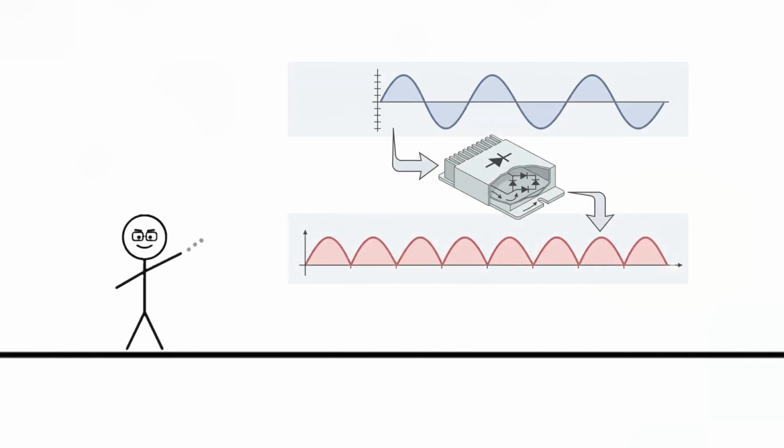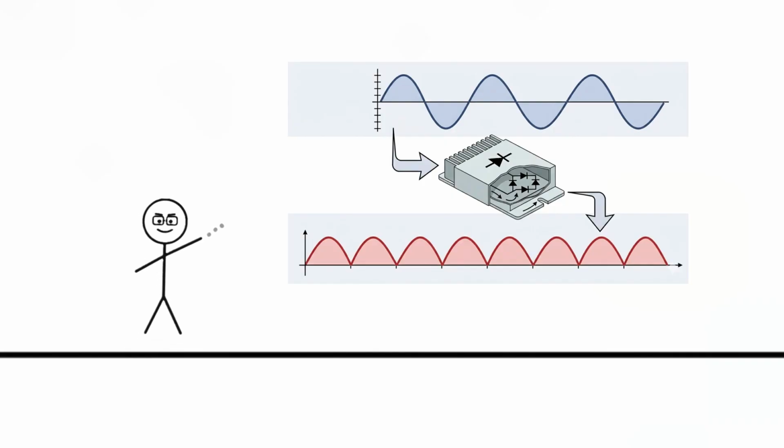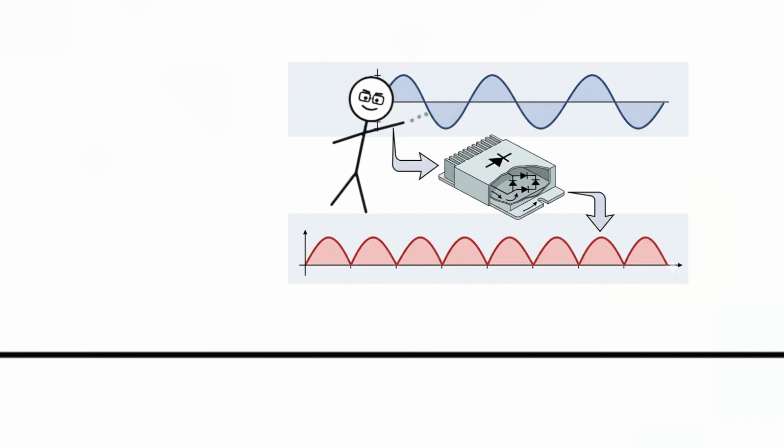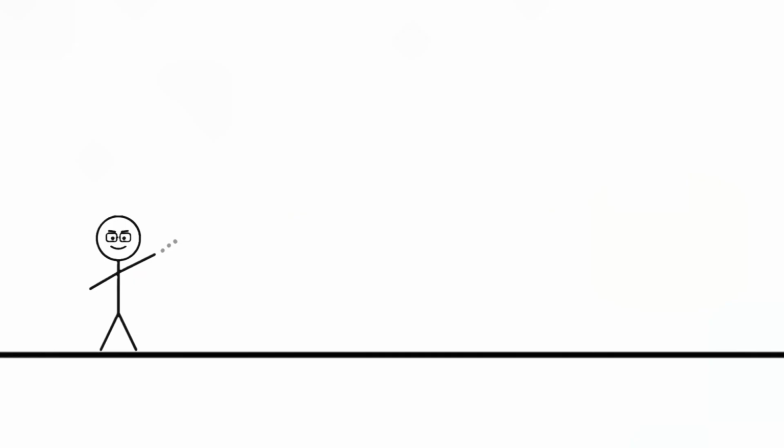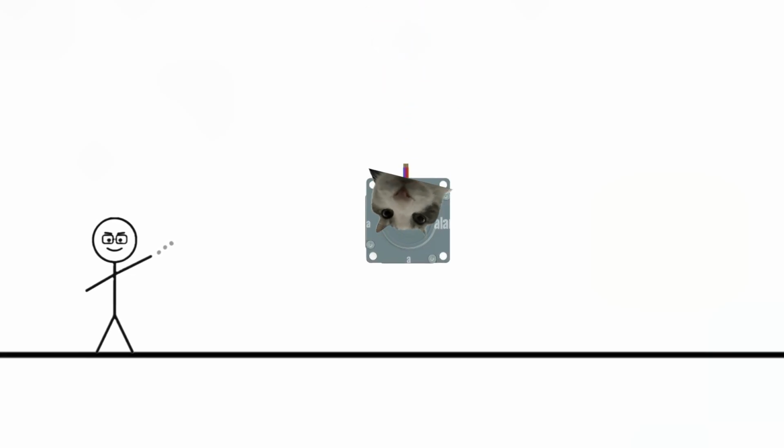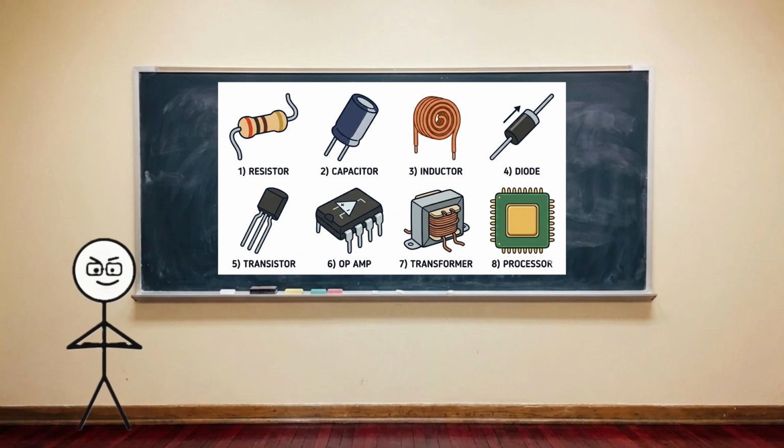In forward bias, the electrons get pushed down the slide and flow freely. But in reverse bias, the barrier widens into a wall that makes it impossible for current to climb back up. This unique physics allows diodes to rectify power by stripping away the backward half of alternating current, AC, to create steady direct current, DC, and to protect sensitive components by acting as a safety valve that slams shut if a battery is plugged in backward, or if a motor tries to kick a dangerous voltage spike back into the system. Now we have completed half of the lesson.